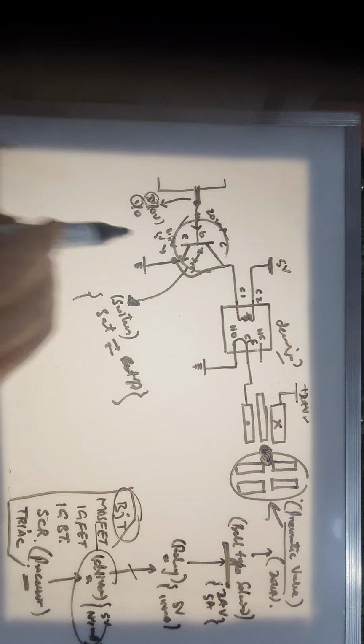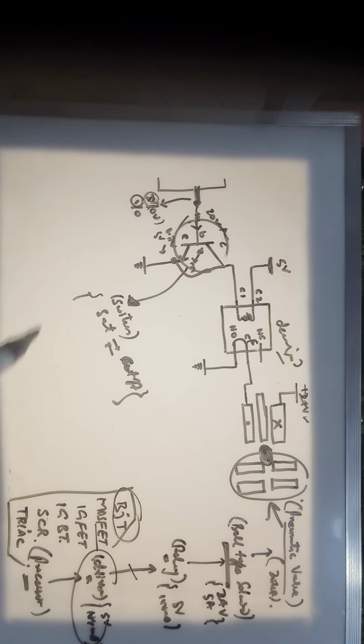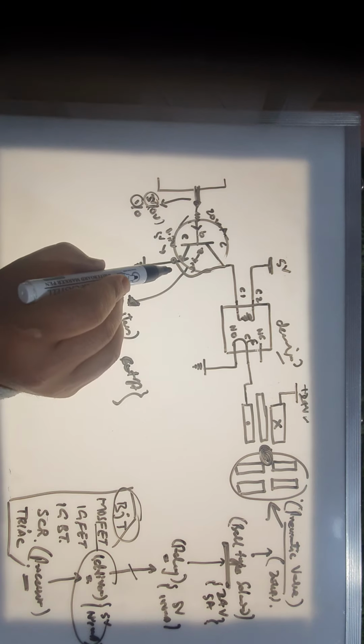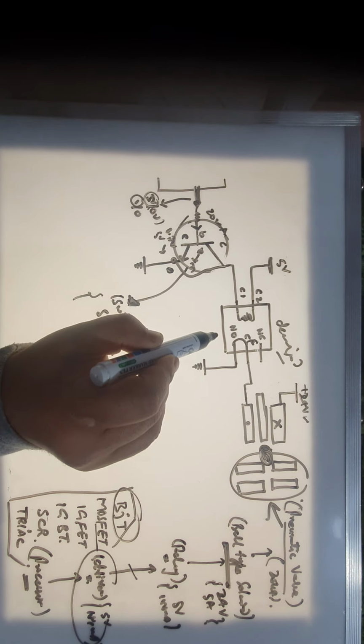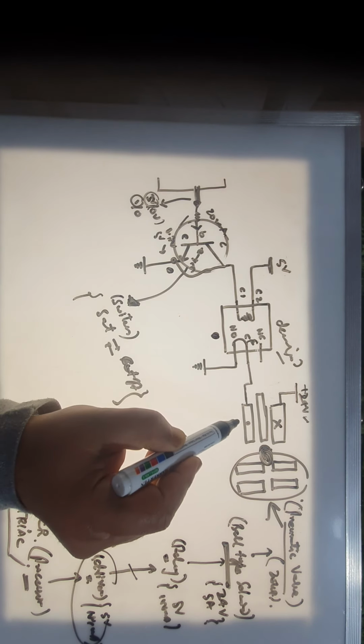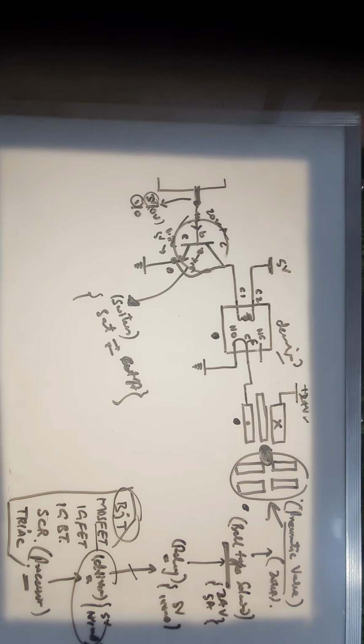So you have now seen there was a 4-stage process to get to this point where we have to get a pneumatic valve that should work for some really big thing. We had to go first through the solid state driver, then move to the relay, after that to the solenoid, and at last to the pneumatic valve. It is how the controls are done, and still we are simply checking out the on-off control. That means the pneumatic valve here is going only from state 1 to state 2.